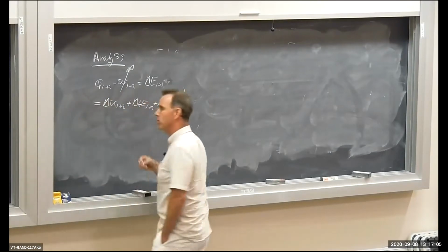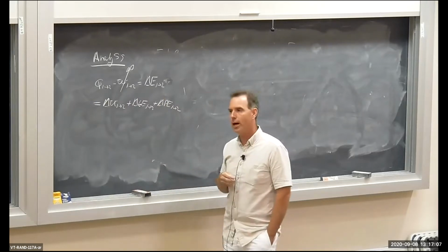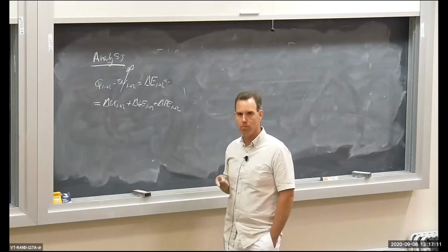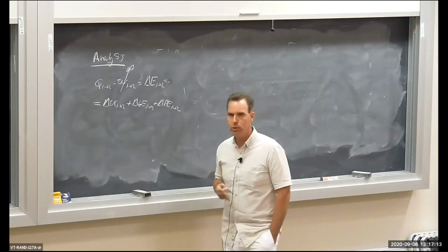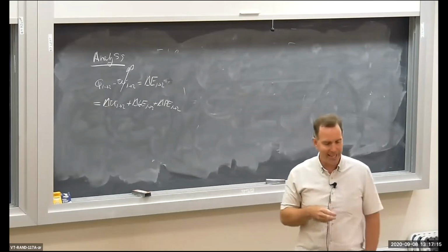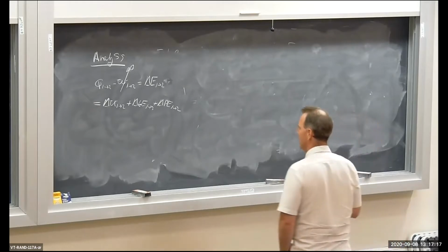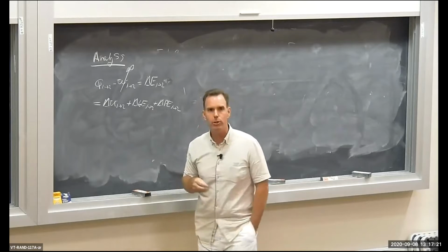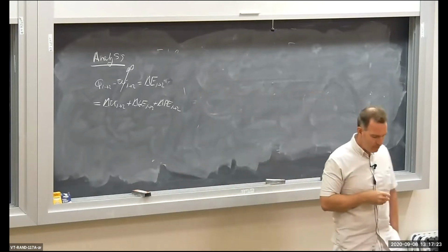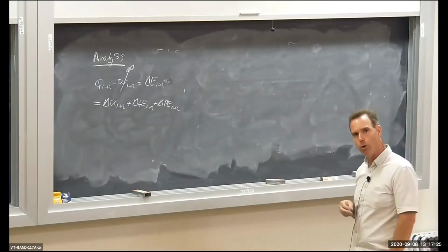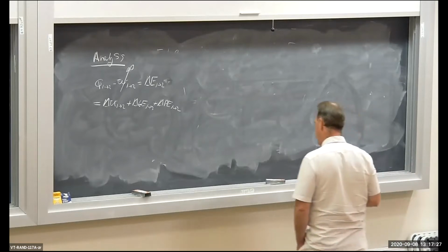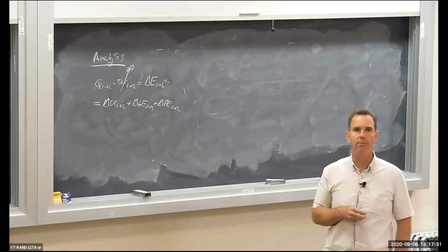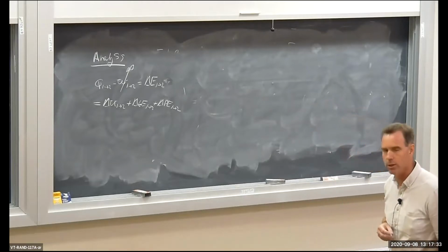The change in internal energy has to do with the change in either phase or temperature of the system. The temperature of the system is definitely changing, so I don't think I can get rid of the delta U term. But I think I can neglect the change in kinetic and potential energy of my air system. I don't get any sense in the problem that the air is moving, accelerating or slowing down, and I certainly don't get a sense that the position of the tank is moving.